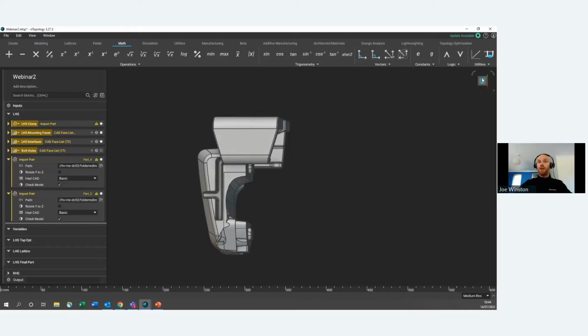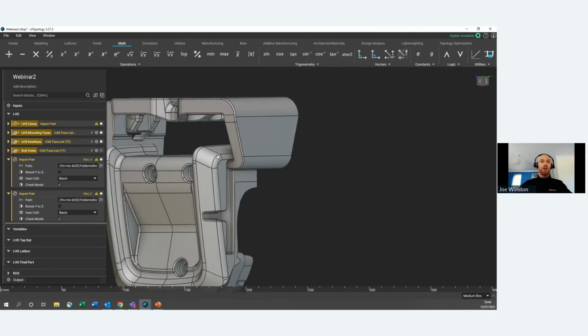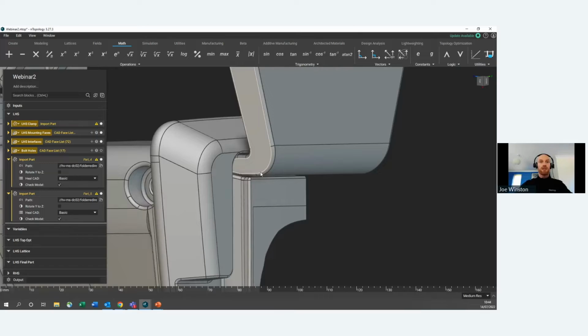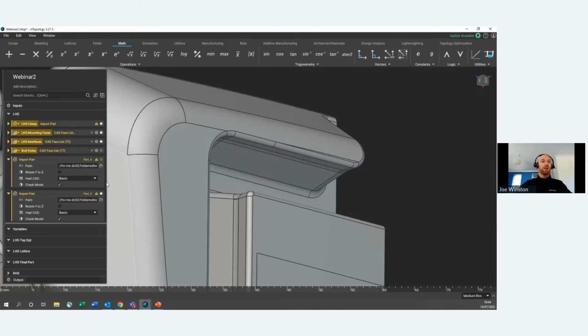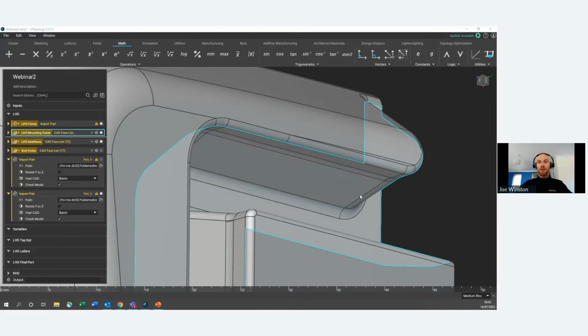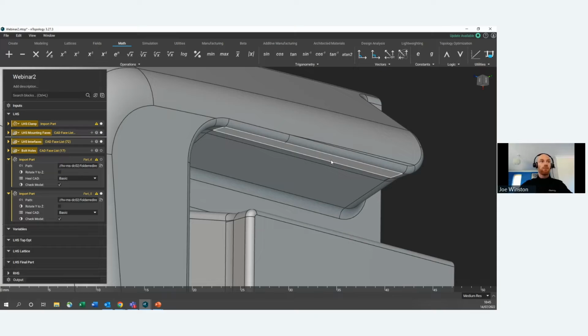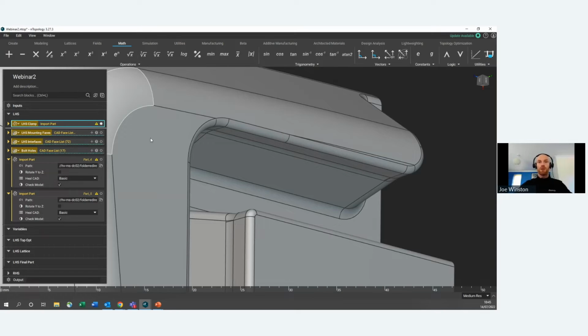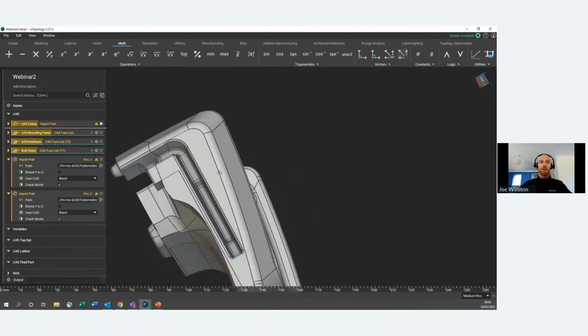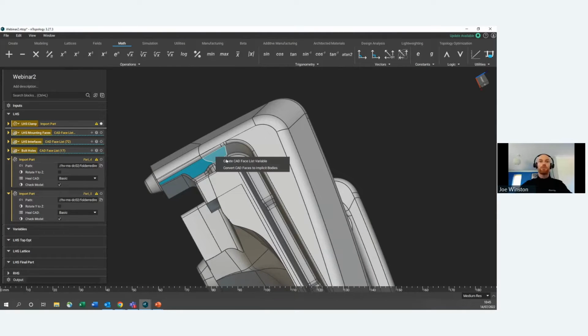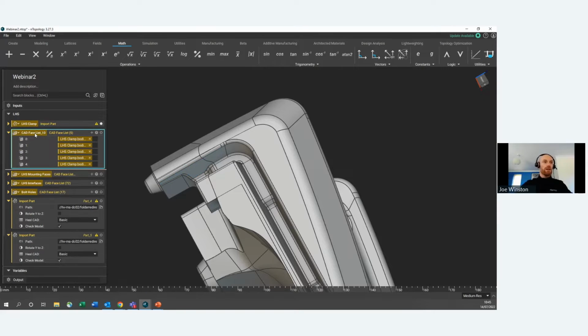So we can see that when this assembly is set up on the robot, you can imagine the robotic arm would be here and the scanner sits here. So the force faces are going to be kind of the interfaces between this bracket here and the clamps. So these faces here. First, make sure I've just got the clamp selected. These faces here, and on the other side, these faces here are going to be the faces for our vertical force.